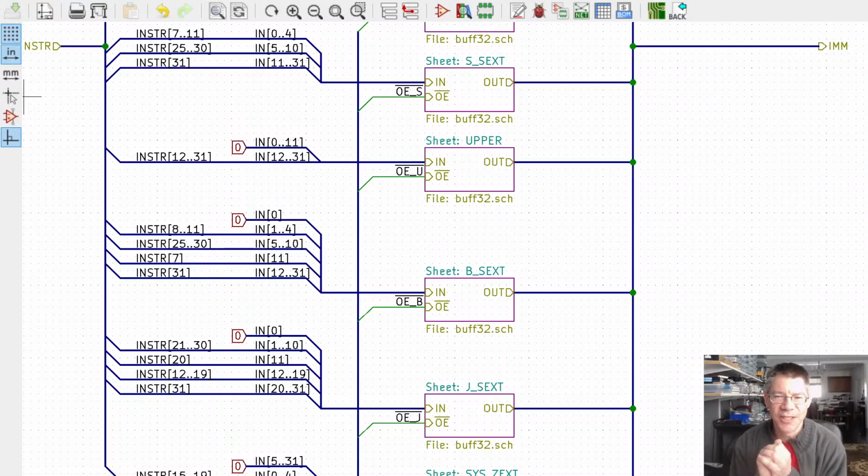Targets for the clock speed, yeah. If you've looked at the previous videos, you'll know that I have a system clock, a machine cycle, and an instruction cycle. Basically, the system clock is the fastest clock. The machine cycle is 6 system clocks, so I basically have 6 phases, and that forms one machine cycle.